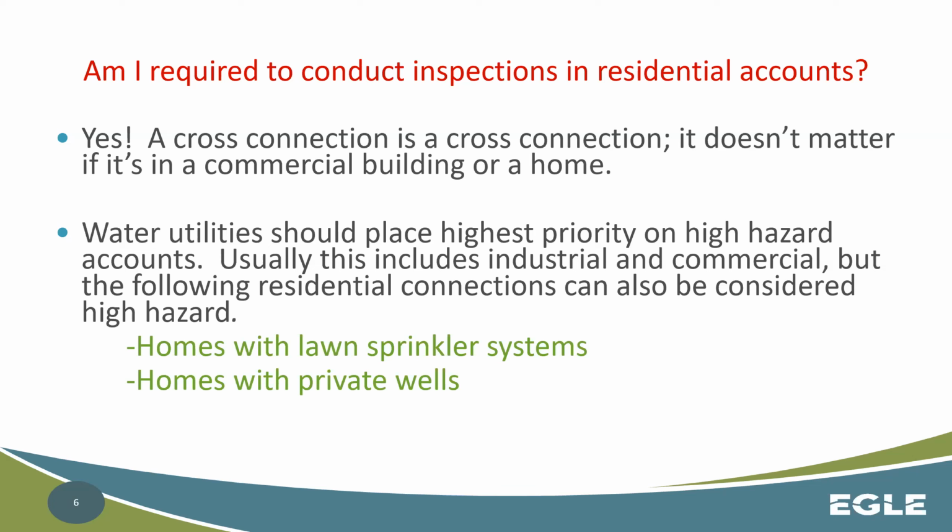And those need to be inspected probably to make sure that there is no connection between the public and that well. Some people only have a private well to use for their lawn irrigation system because they didn't want to get rid of it. You need to make sure and ensure that there is no connection between those two.